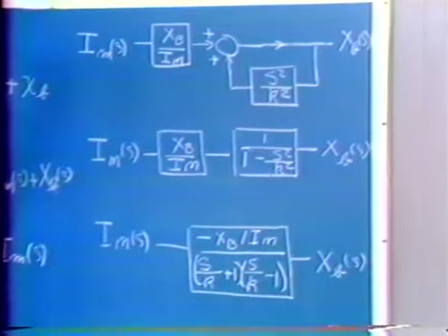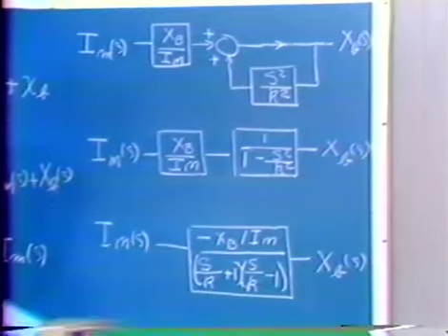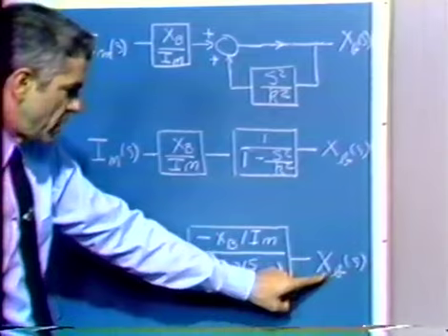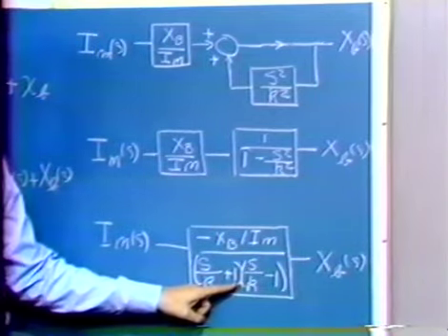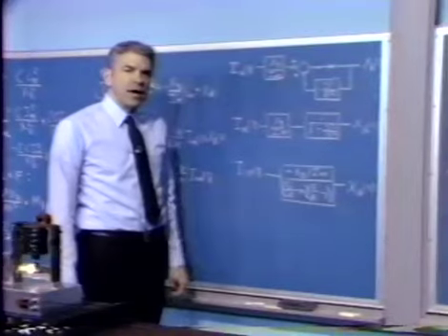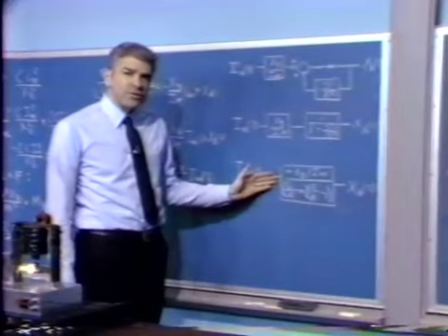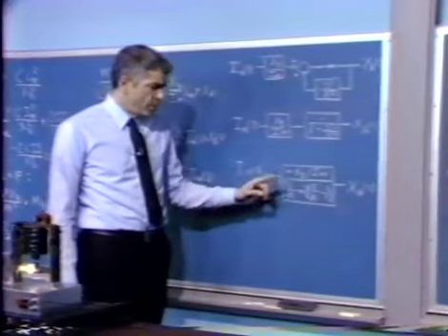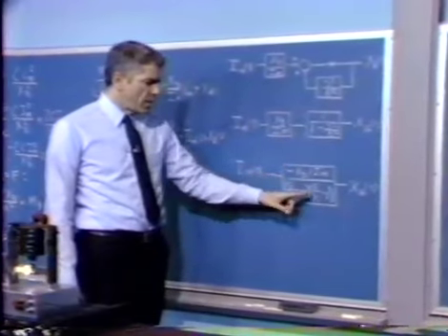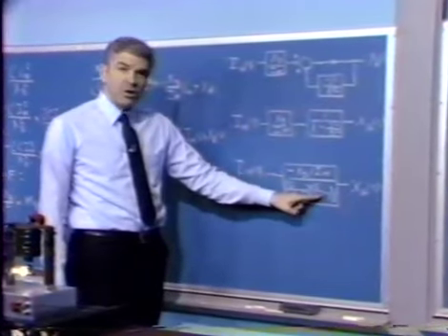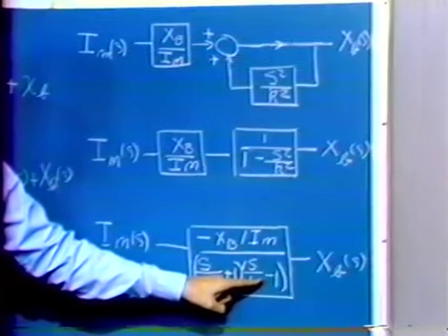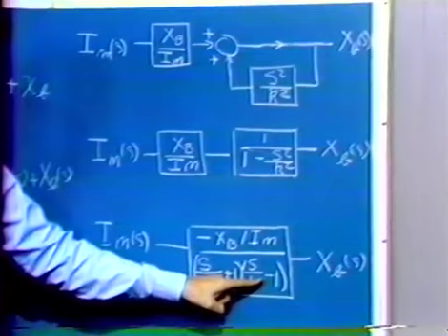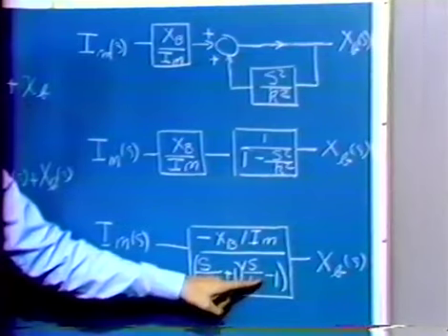And so now we have a fairly convenient form for our block diagram that shows the relationship between ball position and magnet current. We notice how the instability shows up here. When we look at the transfer function that relates ball position to magnet current, we notice that it has a pole in the right half plane. And we anticipate as a consequence that we get exponentially growing responses. And of course, that's what happens.